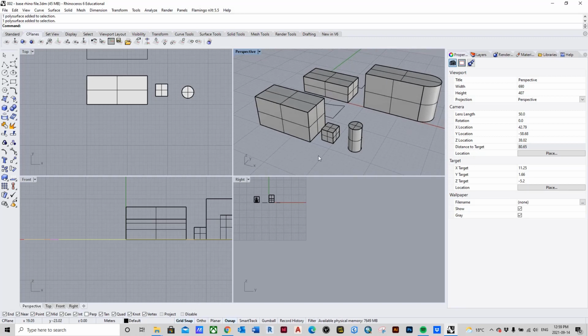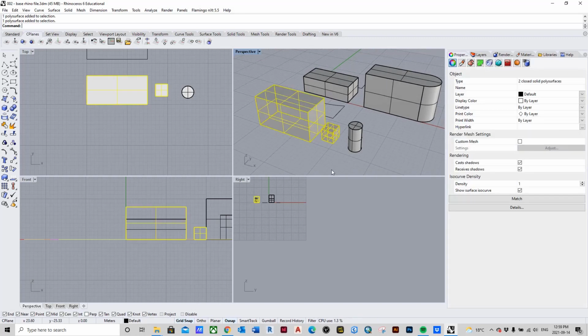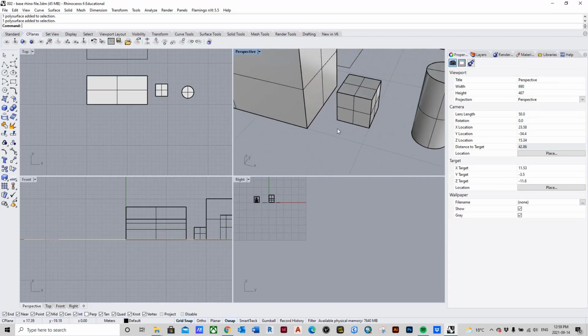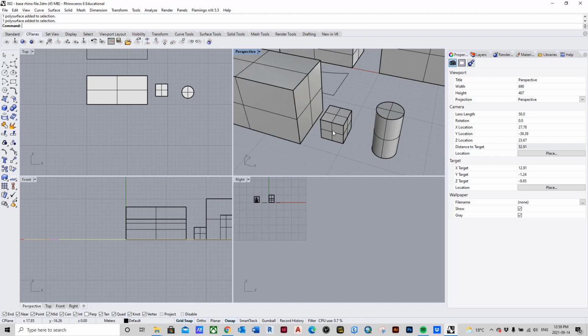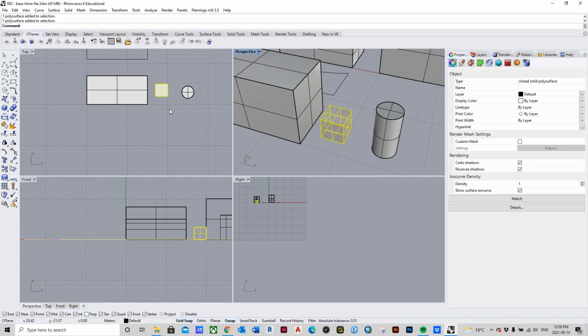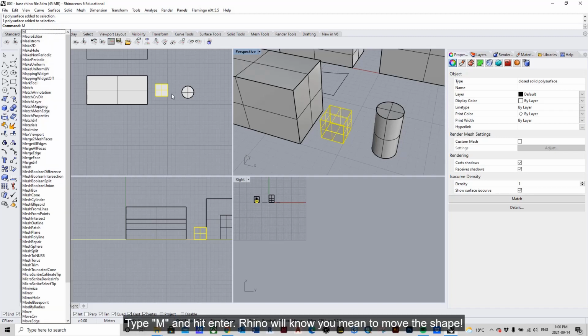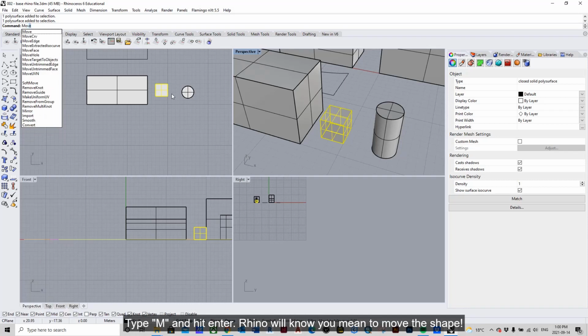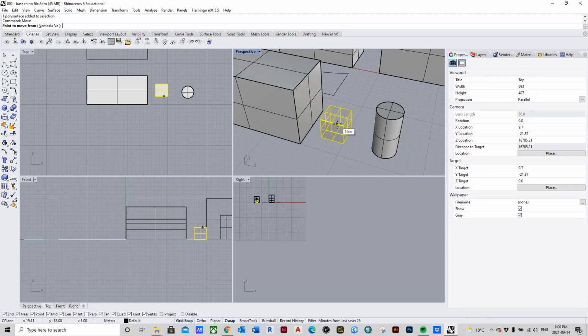Now let's say we want to combine these two shapes. With BooleanUnion, we can do this very easily. So let's grab this smaller shape. We'll select it. We're going to use the move tool so that the two are actually touching and there's something for them to combine together. Type M for move, V-E. Hit enter. This is where it's nice to have the O snaps on, because we'll snap to this corner. See, we'll grab it right there. And we'll move it right over there like that.